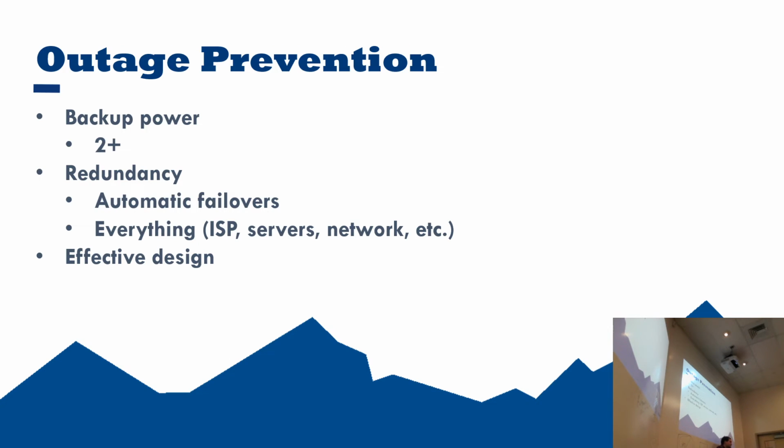All right, redundancy. Make sure that everything's going to automatically fail over. If you have multiple UPSs, the idea is, I'm going to draw the back of a server rack here. Okay, so in general, this is a server, okay? We got 2 power supplies on it. All right, we have a UPS down here, and we have a UPS down here. So let's say this UPS is connected to the main, and this one down here is connected to the diesel. Okay, so you want to have the one from the main powering one power supply, one from the diesel powering the other power supply.